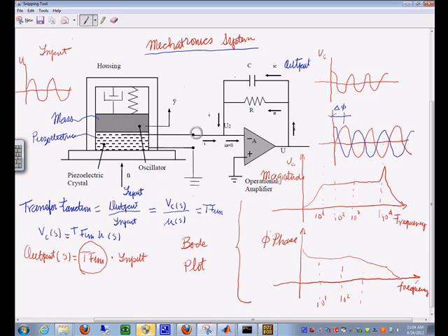But in order to measure this voltage, I need this amplifying circuit. Now, the way this works is this device in here is called an operational amplifier. It has external power so that it can actually amplify the signal that comes in here to what you get out here. In order to achieve this, it's set in such a way that the current here is 0, but the voltage is not.